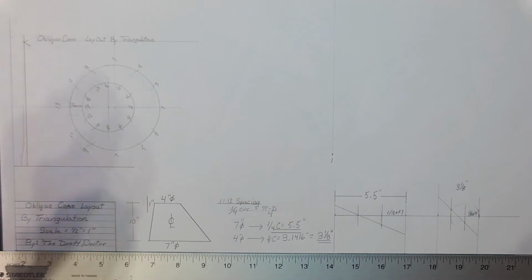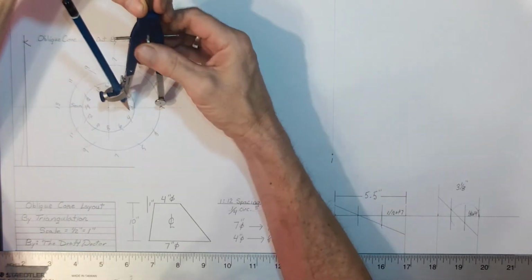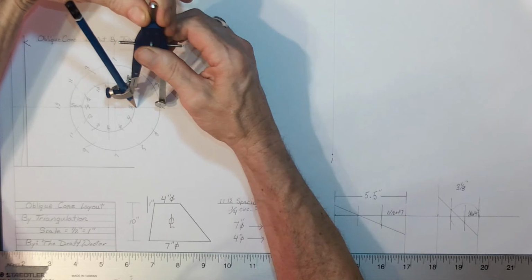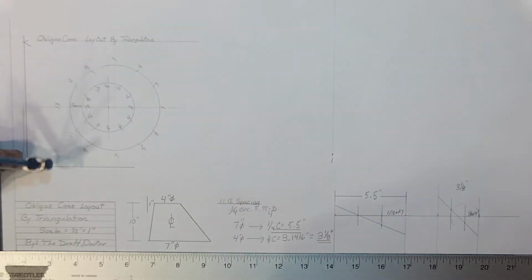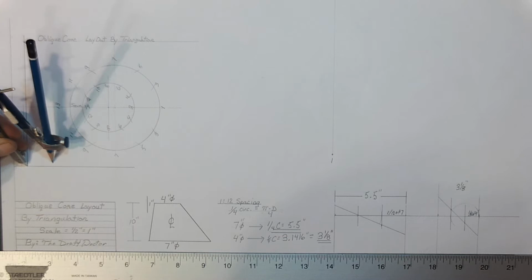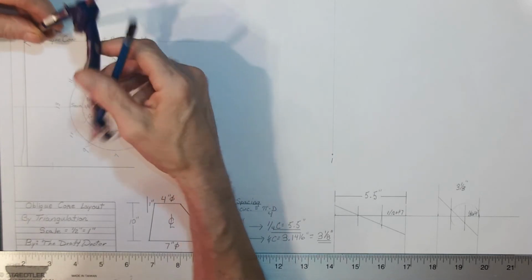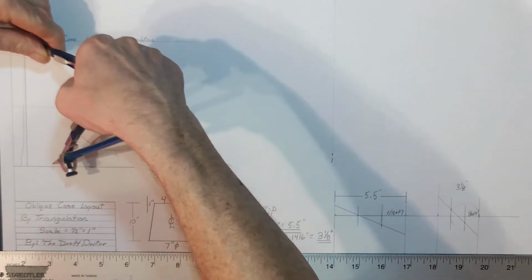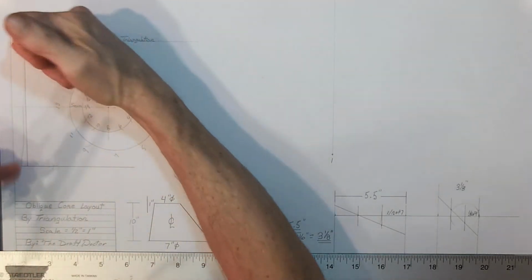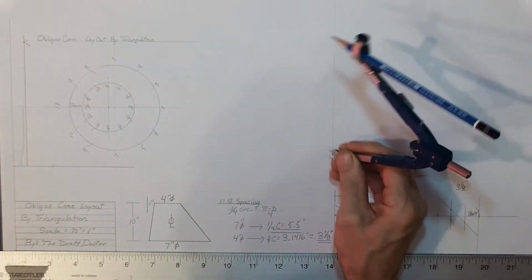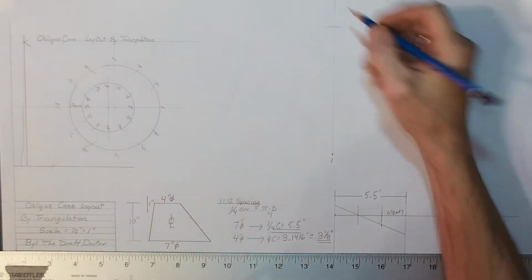If I take my plan view of 1 to 2, and now I'm going to triangulate that plan view of 1 to 2, its true length is the hypotenuse that we find when we plot it on our true length triangle. It's falling this much over these 10 inches. Its true length is that hypotenuse. So now from 1, I can plot point 2. I have 2.